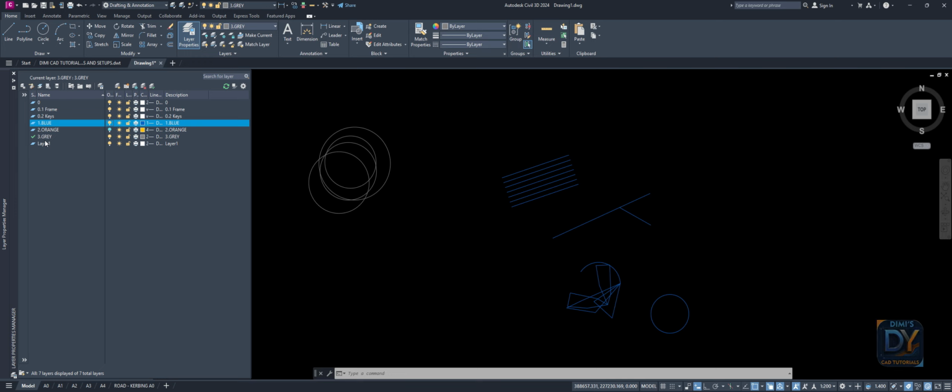You can import your DXF file into your controller with only a couple of layers, which makes your life much easier to set anything on site, by being able to focus only on the information you need, not having hundreds or thousands of objects. I've seen that many times. It makes your kit lag.